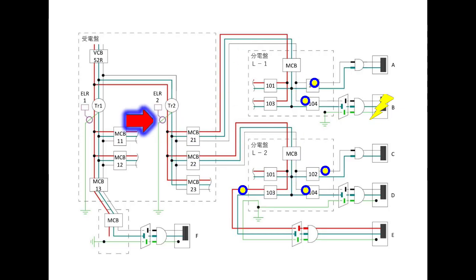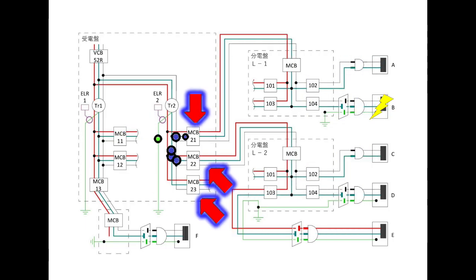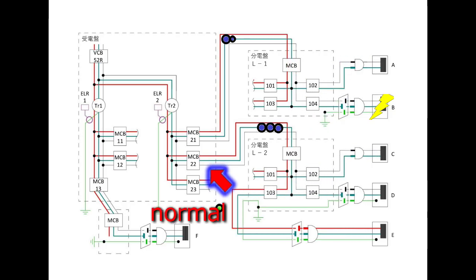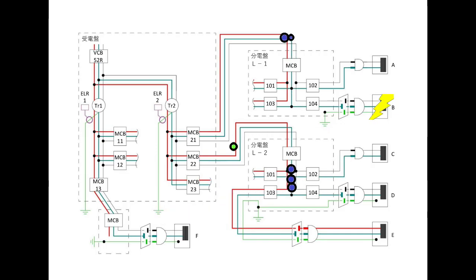First, measure the leakage current in the ground wire of TR2. This is to find out if the fire alarm may be malfunctioning and how much current is leaking. Next, pinch the 3 breaker wires closest to TR2 with a clamp meter. A circuit that is leaking current will display a large current value. This is because current is leaking, so the amount of output and return does not match. A normal circuit has both the wire going to the device and the wire returning, so if there is no current leakage, a value close to 0 will be displayed.